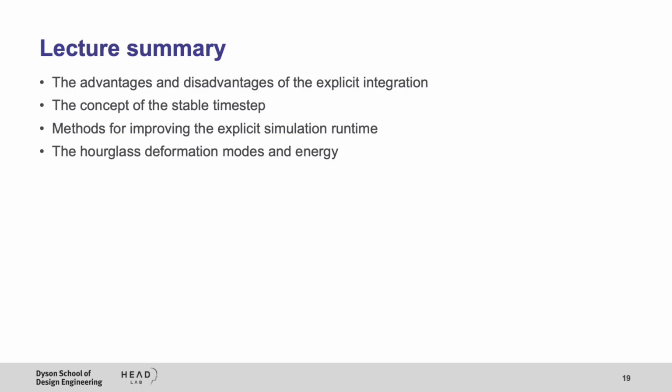So in summary, in this lecture, we learned about the advantages and disadvantages of the explicit integration. We learned about the concept of the stable time step. We learned some methods for improving the explicit simulation runtime, in other words, increasing the stable time step. And finally, we learned about the hourglass deformation modes and energy and the rule of thumb in terms of this artificial energy generated by hourglass deformations. I hope you have enjoyed this lecture. Thank you.